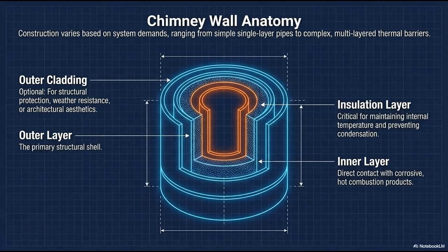This sets up a profound architectural showdown between traditional brick chimneys and modern metal flues. Here's where it gets really interesting. Because traditional brick chimneys are the absolute worst-case scenario for a modern boiler. They are the loser in this showdown. Big time. First, just structurally, they are usually rectangular, which creates terrible aerodynamic drag in the corners. But the real killer is their thermal mass. The sheer weight of them.